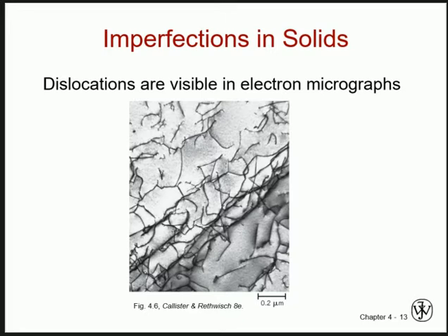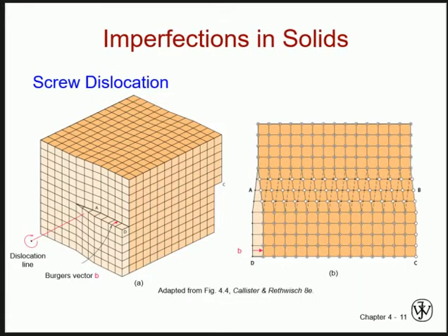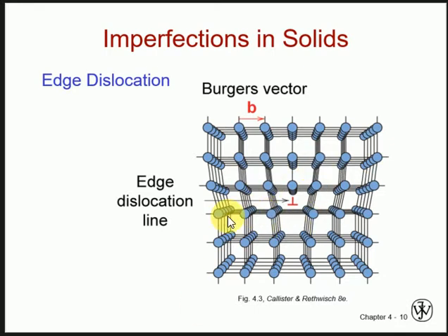Okay, so the length of the dislocation will be smaller than, of course, the grain or the crystal of atoms, but they usually tend to move in a coordinated way. Dislocations tend to form within a material, and a dislocation is simply, you can say, an extra half plane which can be formed within a system during the solidification process, or it may also form during the deformation of the material.